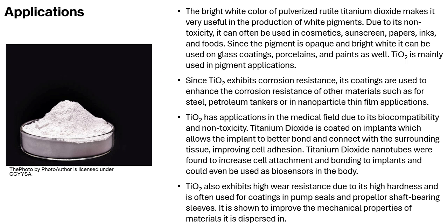Since TiO2 exhibits corrosion resistance, its coatings are used to enhance the corrosion resistance of other materials, such as steel and petroleum tankers, or in nanoparticle thin film applications. TiO2 has applications in the medical field due to its biocompatibility and non-toxicity. Titanium dioxide is coated on implants, which allows the implant to better bond and connect with the surrounding tissue, improving cell adhesion. Titanium dioxide nanotubes were found to increase cell attachment and bonding to implants, and could even be used as biosensors within the body.